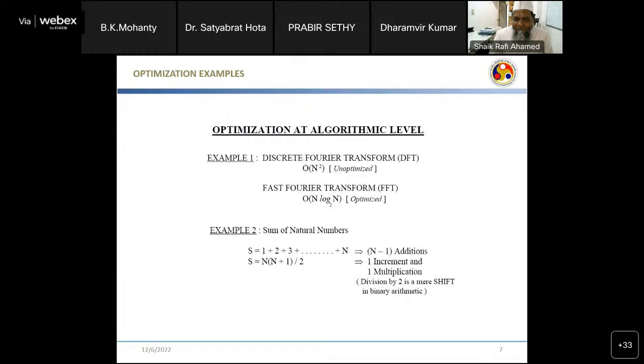Sir, can we use this distributed arithmetic to build VLSI adders and multipliers, these circuits? Yes, you can implement a multiplier by using distributed arithmetic. We hope it will be faster. But if you just implement a conventional multiplier, it's not worthwhile. If you take a system consisting of a lot of multipliers and implement it using DA, then you'll get benefit out of that system. That you can publish somewhere also. But if you take just a simple multiplier for experimental purpose, you can do it.